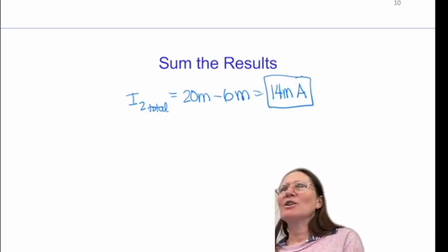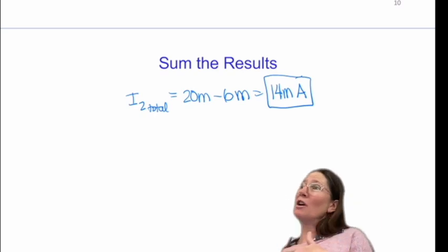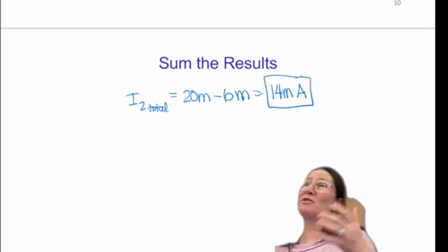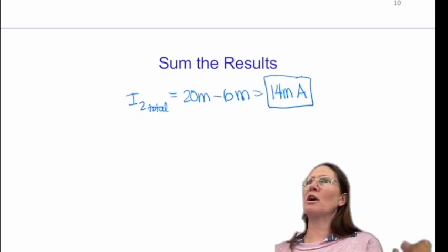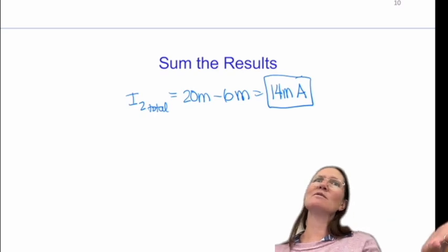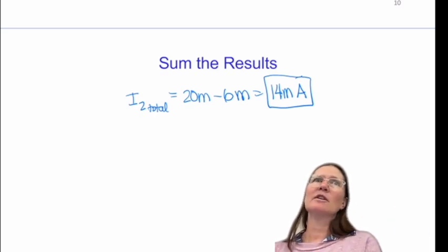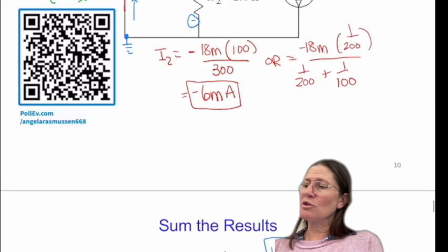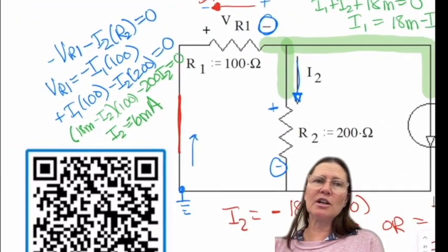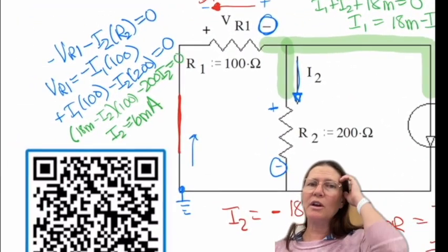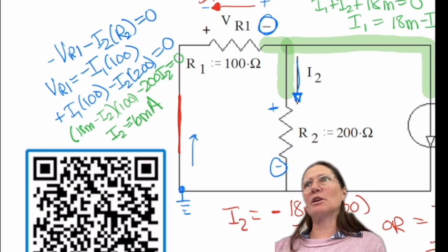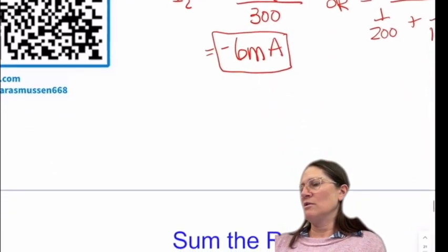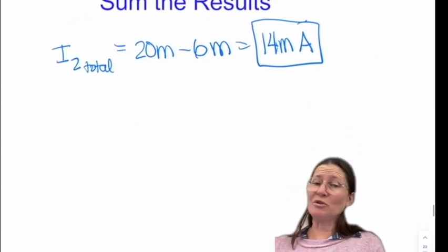Okay. So a few more involved steps as far as you have to break up the circuit, but most of the time when you break up that circuit, it's going to be something simpler, either Ohm's law, you could see it's a voltage divider or current divider. Otherwise, you could do the same steps that I did here as far as taking the loop and include the voltage source and then taking the current summation, and get the same result of 14 milliamps.